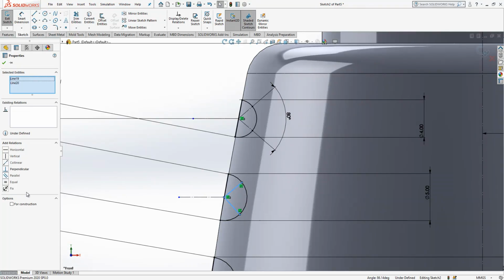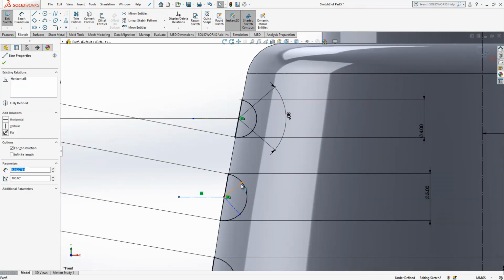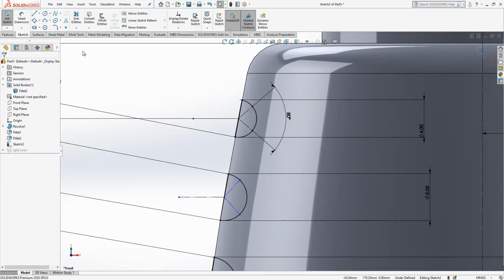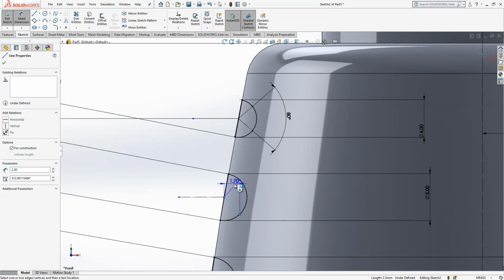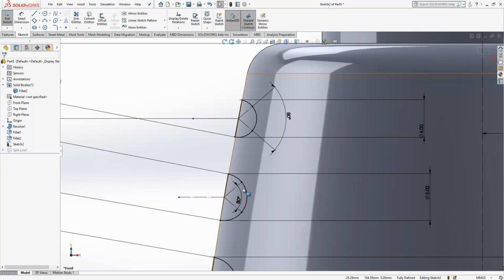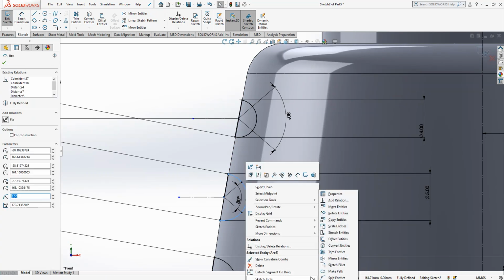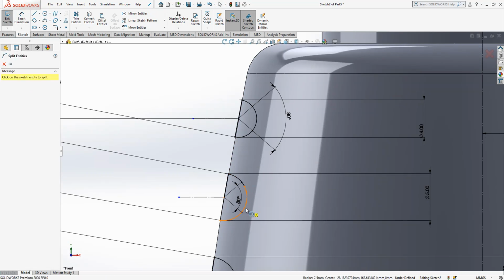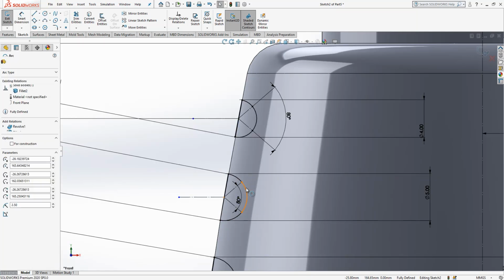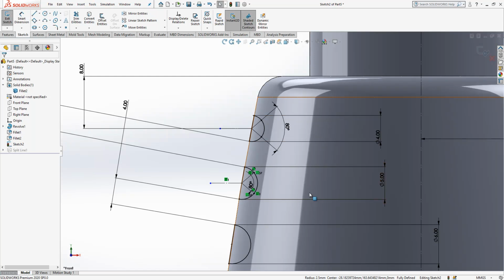These are both construction geometry, and then these 2 points will be symmetric. Now control is pressed. Okay. Angle will be 80 again. Right click, split entities. It's good that we get some error, and then that helps us to develop a different way of dealing with difficulty.